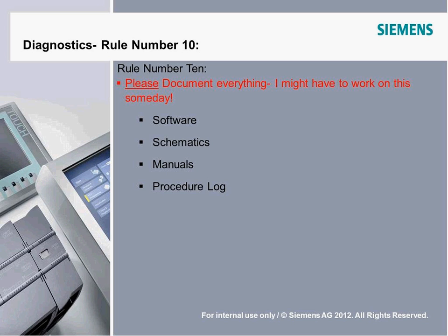Localize the problem. Try to get away from looking at the machine as a single entity and take it down to the subsystems that typically make up tools. Like there's oftentimes motion control and temperature control and valve gas flow and other different subsystems of a machine that, if we can focus in on those, it helps us out quite a bit. It gives us a lot less variables to deal with.